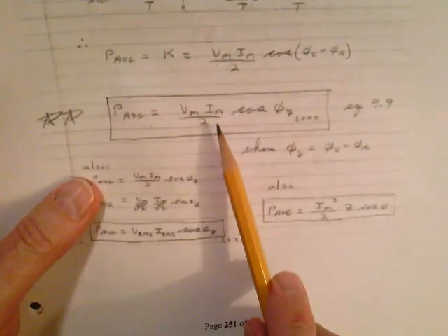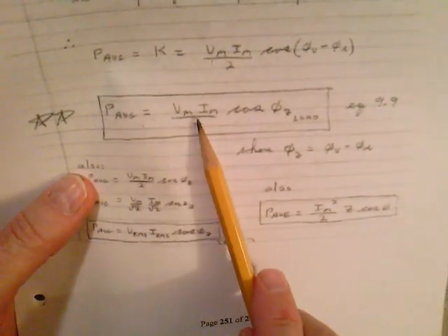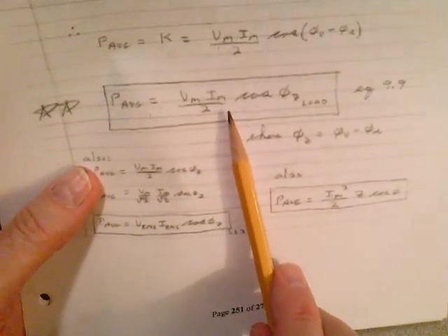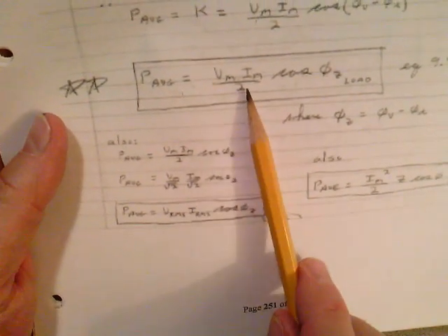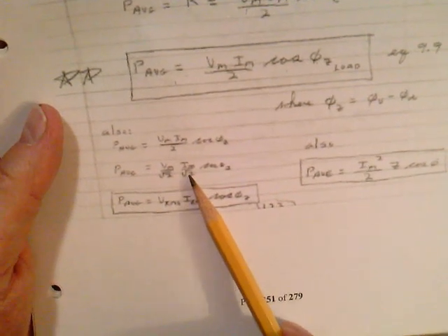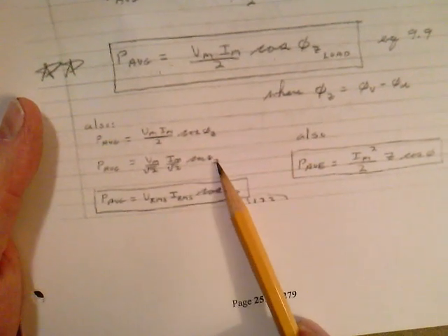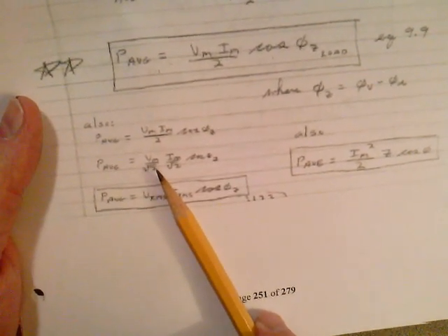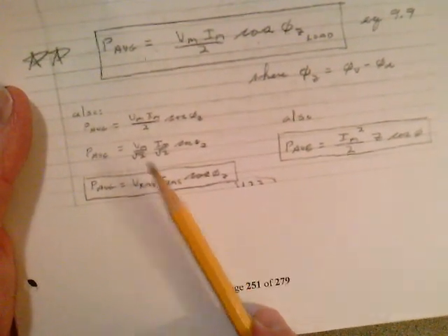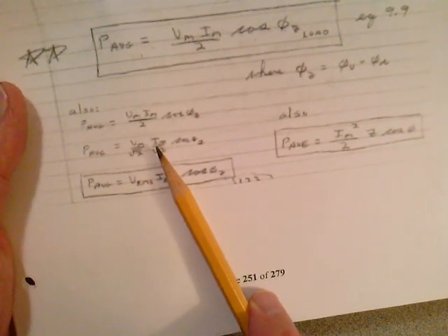Also, it can be shown here, if you take a look, there's one equation for the average power or the true power. You can use that if you have the impedance angle, if you know Vmax and you know Imax. Do you see here that what you can do, and I showed you on the page here, is you can take this 2 here and separate it into square root of 2 times the square root of 2. And you put Vmax divided by the square root of 2 times Imax divided by the square root of 2 times the cosine of the phase angle. Well, that's the RMS value. That's the effective value. Vmax divided by the square root of 2 is 0.707. Same thing with Imax divided by the square root of 2. You get a 0.707 in the numerator.